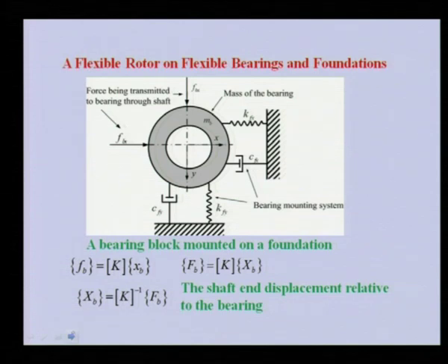So, I am coming to the free body diagram of, let us say, the bearing. So, this is the bearing mass. In the previous analysis we did not consider the bearing mass. Now, this is the bearing, and the journal we have removed from the bearing. So, obviously the fluid film forces coming onto the bearing mass are Fbx in the x direction and Fby in the y direction.